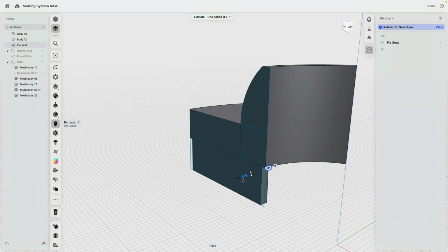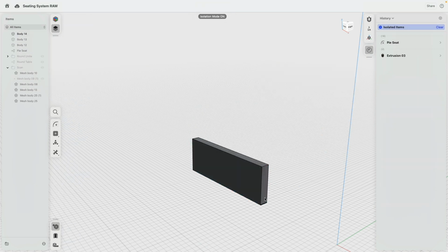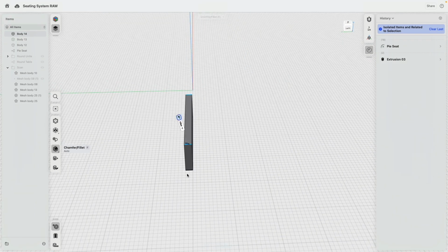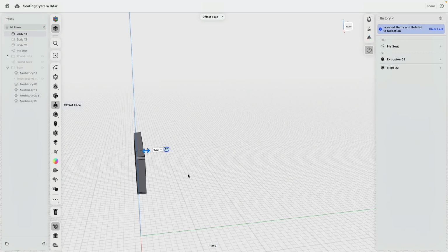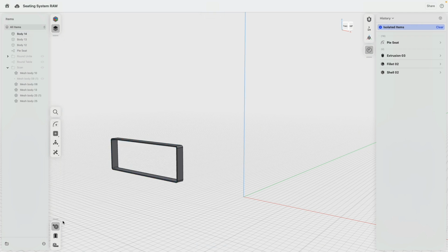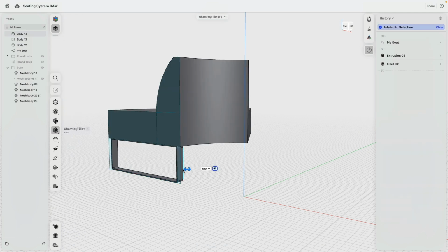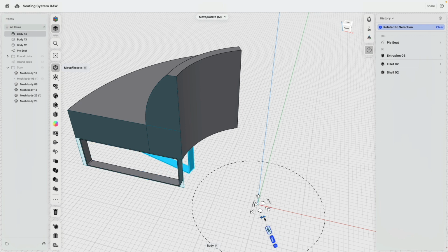Now here we can bring in our leg. There we are. We will continue working on this leg at this point because then we need to make multiples. And 1/2 inch and 0.25 shell. There we are, and unisolate. And then I can select the leg, move the widget of the move command to the center, and then click copy and say 60 degrees, I think.